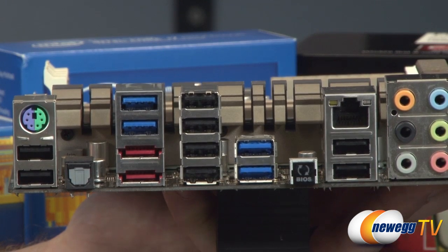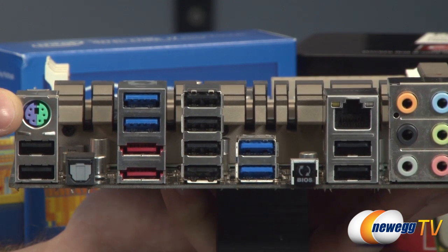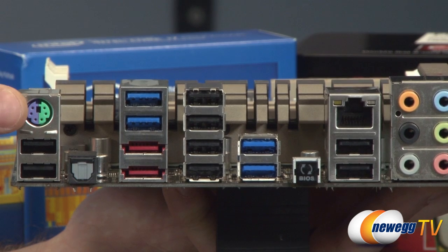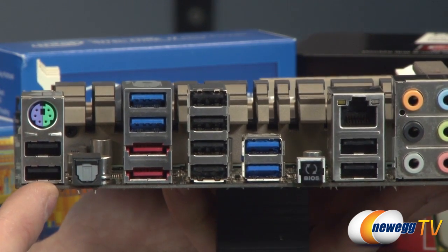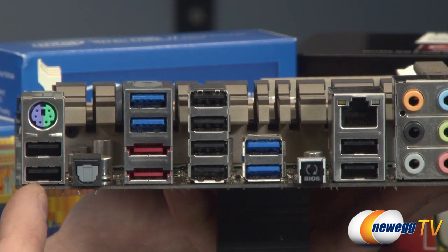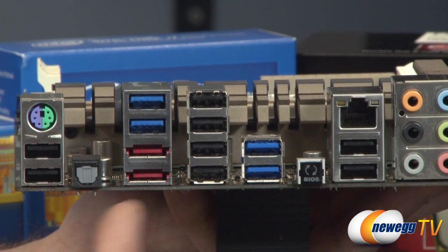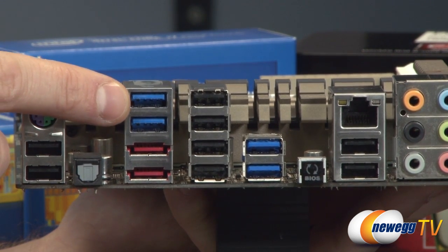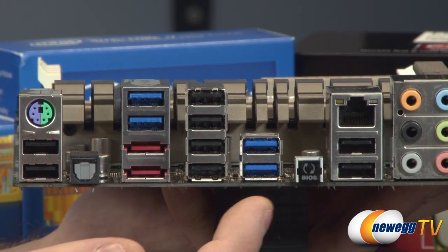So just to go over some of the connection points here, we have this purple and green port. That's a PS2 port, which is also a slightly older connection point, but if you have a mouse or a keyboard that uses that and you really like it, you might want to make sure that you have that on your motherboard. USB, which is almost always going to be either USB 2 or USB 3 right now. USB 3 just gives you additional bandwidth for faster connectivity and transfers. But this one has a bunch of USB 2.0 ports, the black ones here, as well as the 4 that are right here. USB 3.0 usually is going to have a blue connector, so those are indicated by the USB 3.0 ports there, as well as down here.